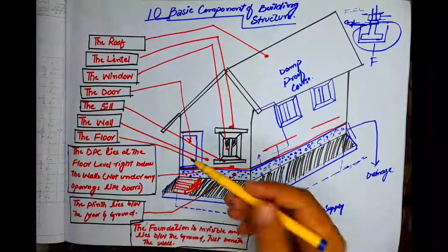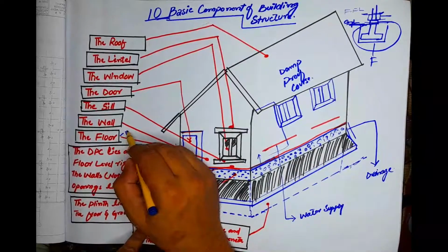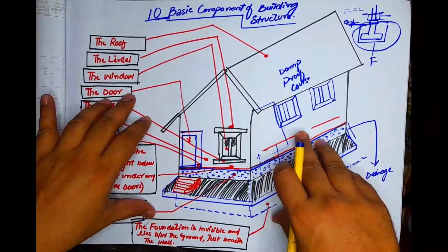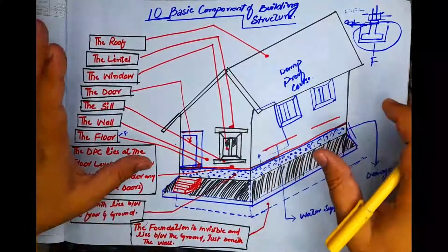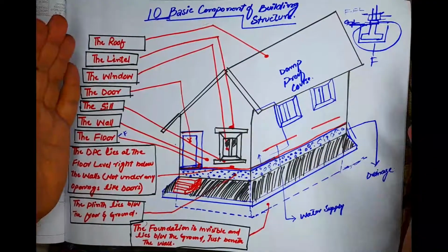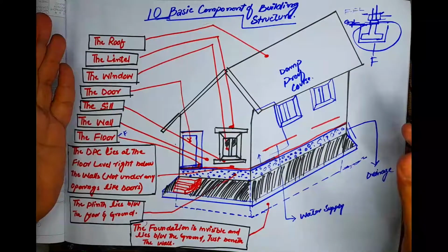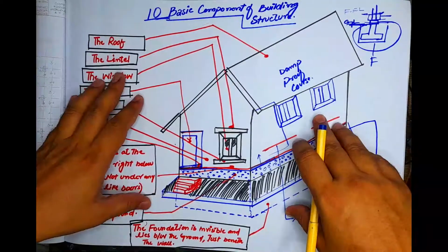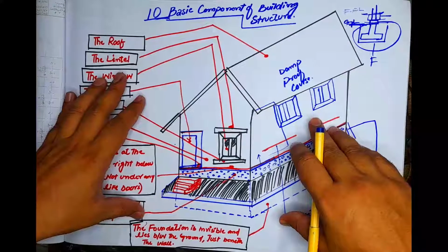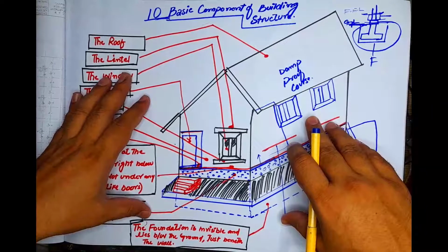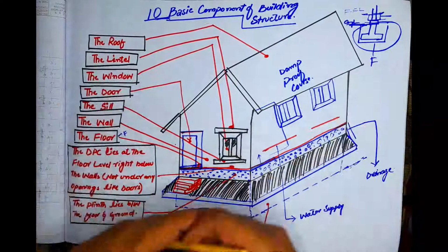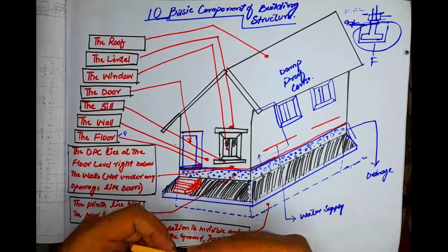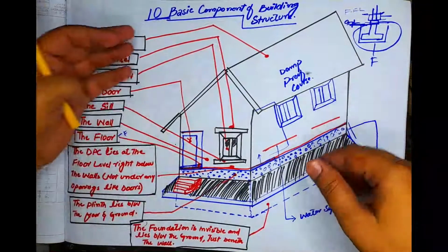The fifth one is floor. The floor is the surface on which we do most of our activities, like carpeting, and we can sit easily on chairs or on the ground surface. Flooring is laid over the filling of the plinth and on subsequent floors. Floors can be done with different materials, but care must be taken that the ground below the floor is well compacted. The floor area must be compacted by a compactor machine to avoid settlement in the building.